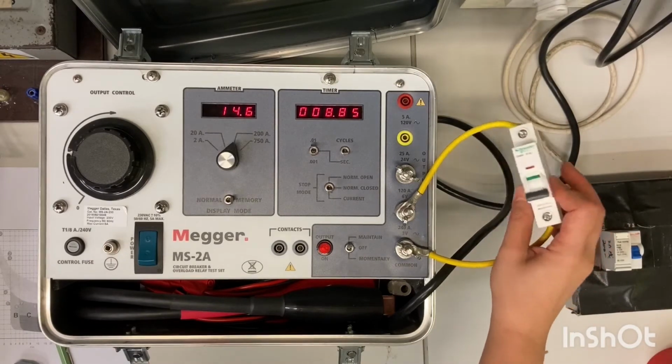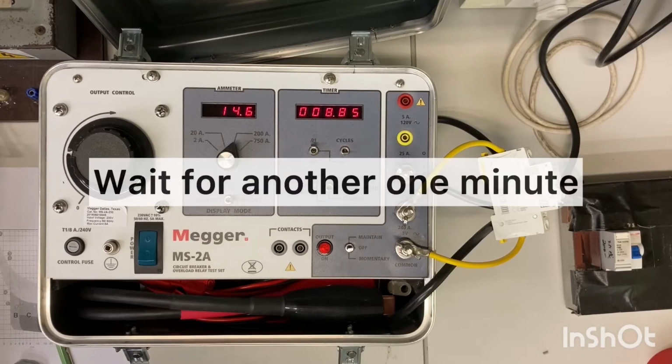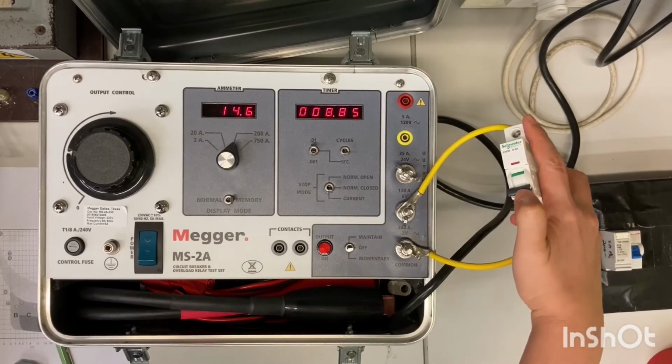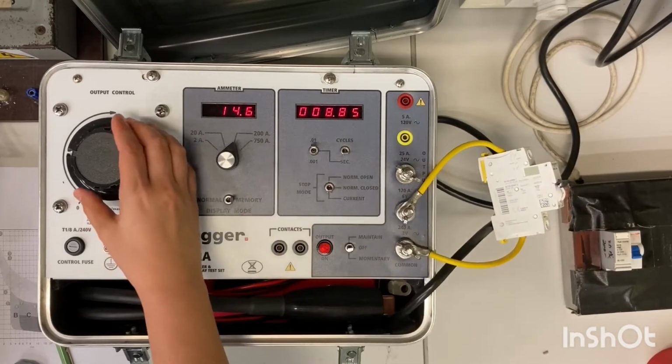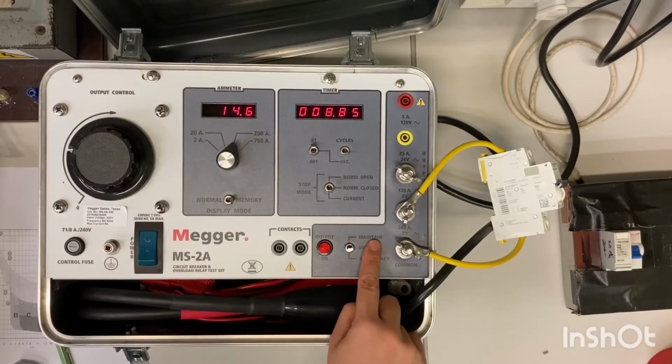So for a current value of 14.6 amp, the disconnection time is around 8 to 9 seconds. So we need to cool down the MCB once again and repeat the procedures for other larger currents.